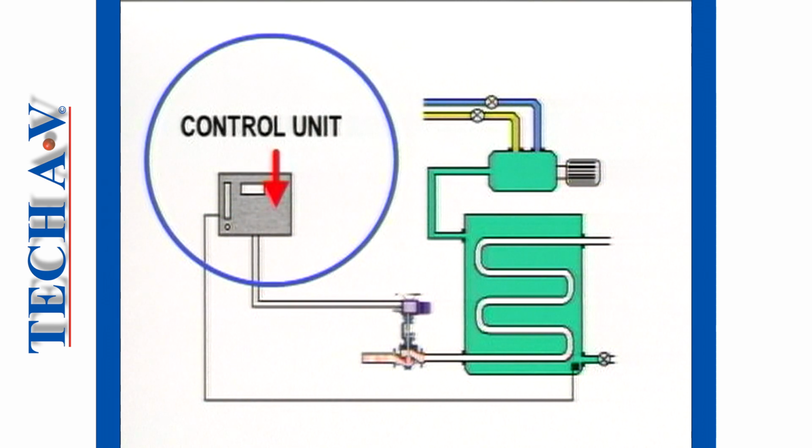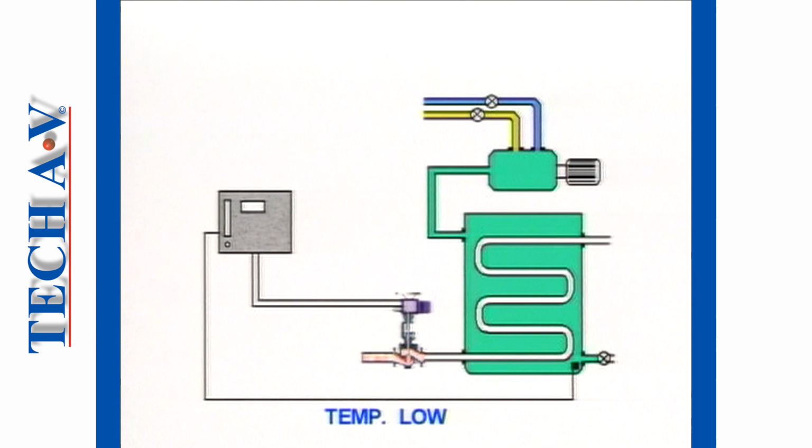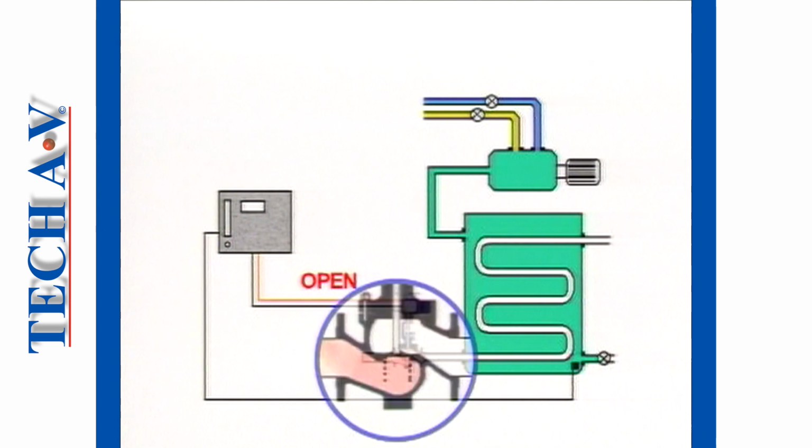Now, let's suppose the engineers decided to maintain the original on-off control unit. However, they replaced the original steam valve with a larger unit to cope with a larger steam flow into the heat exchanger. Here's what is likely to happen. On startup, the temperature sensor, as before, will signal a low temperature, and the set point controller will cause a full valve opening.